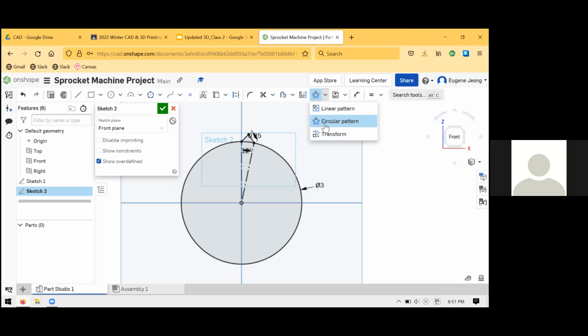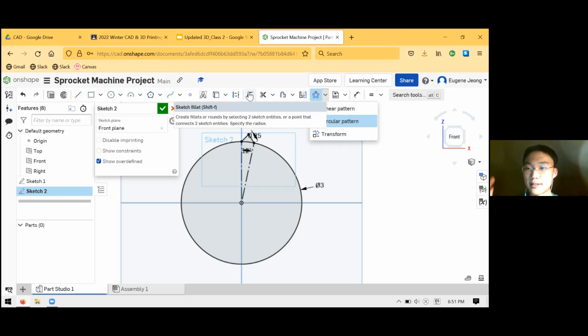What does the sketch fillet do? Does it just make the edges circular? Yeah, because it looks like a triangle and then it's carving out a bit of it to look like part of a circle. If you remember in our 3D space two weeks ago, we used the fillet tool, and that takes the corners you select on your 3D objects and rounds them out, like you sanded them over. A sketch fillet does that, but before you go into the 3D workspace. While you're still in your 2D sketch, it takes your corners and turns the sharp corner into a rounded part. Oh, okay. And so when you turn it into a 3D part, it'll already have the fillets.